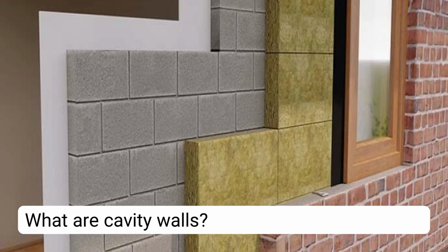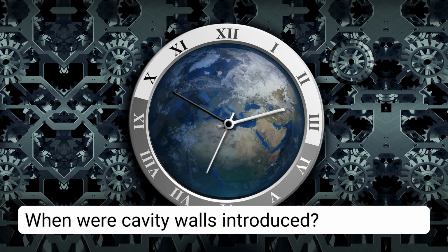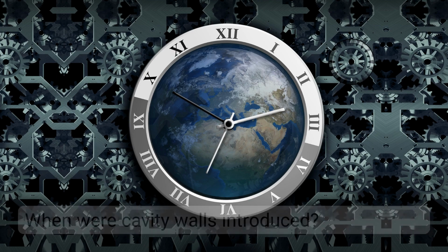What are cavity walls? In buildings made after the 1920s, the external walls have two skins, or layers, with a small gap between them. This little gap is called the cavity. The cavity must be filled with insulating materials to protect a property from heat loss and to comply with the regulations. When were cavity walls introduced?